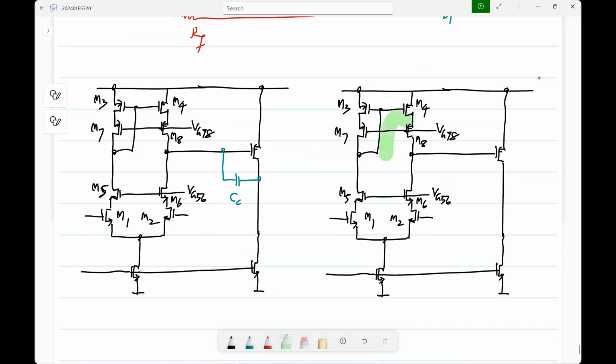So, okay, at least look at this part of the circuit. What is this? If you look at M6 or M8, you already have common gate amplifiers, right? That is, if you connect the input to the source, the output is already connected to VO1.